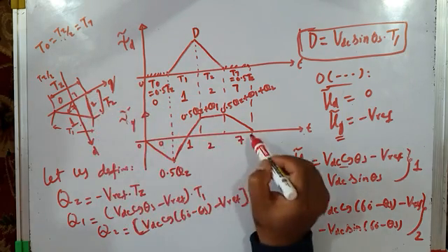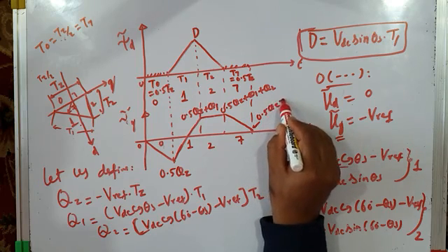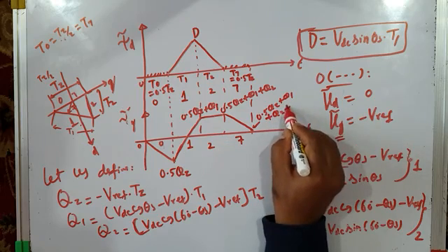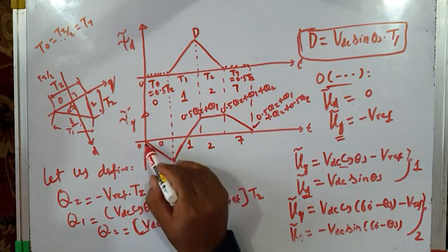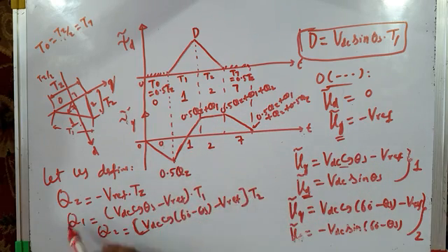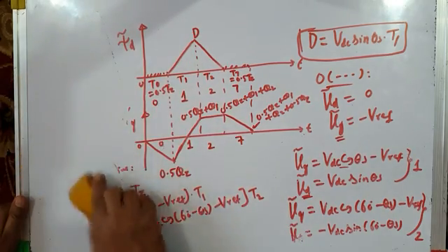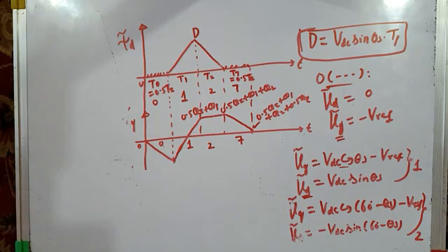And then null vector 0 is again applied. We reach here, and here it will be 0.5 Qz plus Q1 plus Q2 plus 0.5 Qz again. That's it. So we have been able to write the lengths of these lines, the magnitudes of these linear lines, in terms of equations, in terms of q axis components of voltage vectors. With this knowledge, we are now ready to determine the d axis and q axis stator flux ripple vectors.